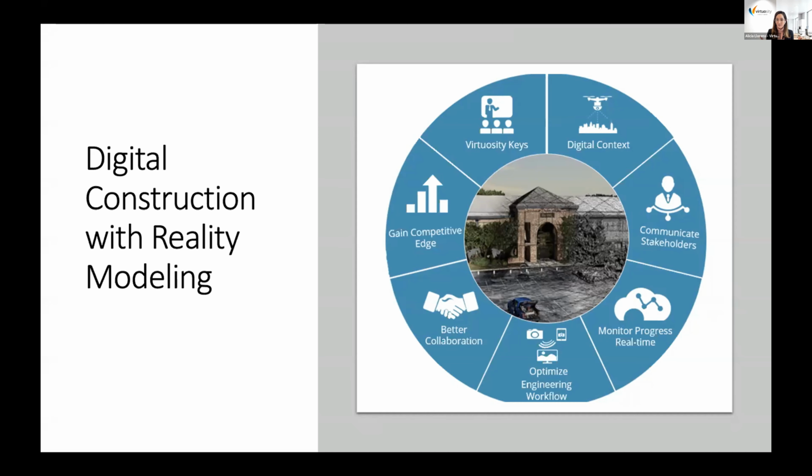For the housing, they do something really cool. They generate a rough 3D model from outsourced data, so LiDAR or orthophotos that they can find, from governmental platforms, for instance, and they create a simple reality model that they import as their 3D flight plan for the mission, and the drone will fly autonomously around the building or the asset. So they optimize the data capture process immensely.